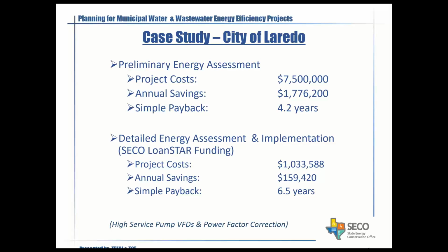So these are VFDs that are not rated at your 460 volts, but are in the 12 kV range basically. These VFDs are the size of a room. These are not the VFDs that you typically see on an HVAC system or small systems. Basically, the pumps are 300-400 horsepower and they require a pretty large VFD, which is what the high service pump VFDs are.